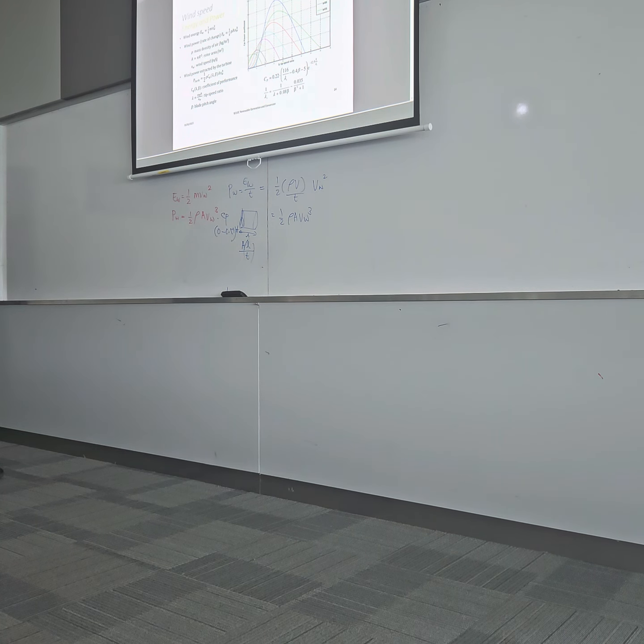Okay, and it can be seen that if we plot a graph of the tip speed ratio and the different blade pitch angles, it's not so clear here, but blue is 0 and this is going up to 17.5 degrees. Okay, so at 0 and at tip speed ratio of 5, you are getting the highest coefficient of performance.